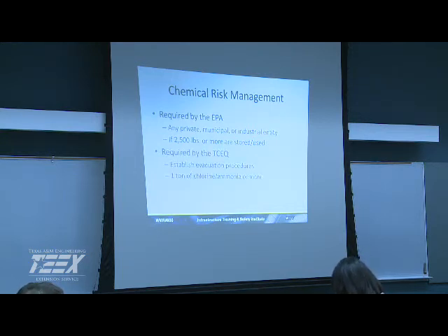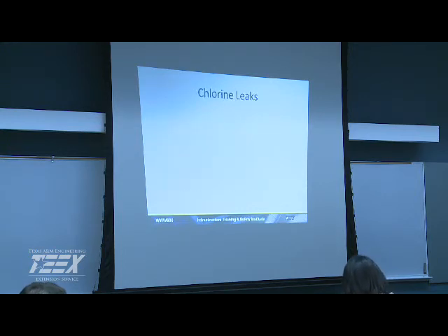You should have evacuation procedures. Even on a simple bleach solution, if somebody gets sprayed with it, if it's under pressure or something, what are you going to do? Do you have a little eye wash station? If you have a spill, how are you going to respond to it? Especially if you're using gas, you've got to really look at more stuff.